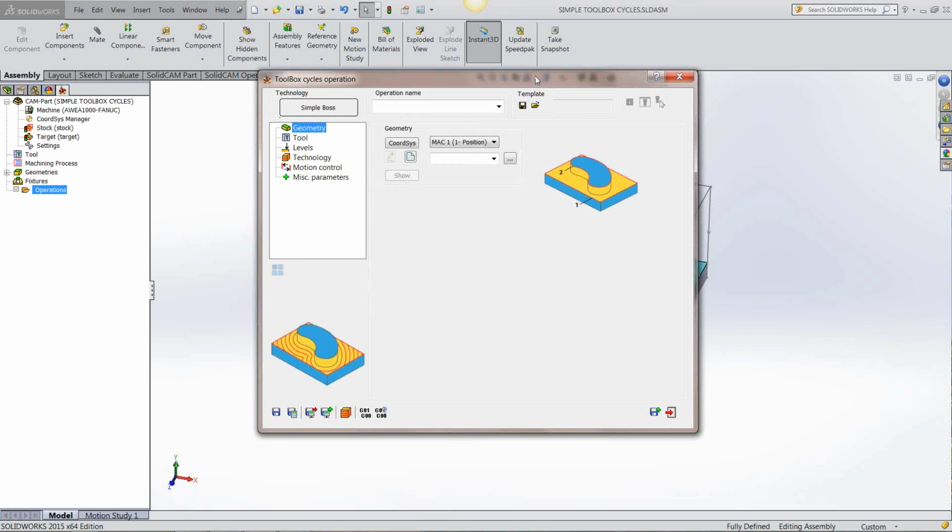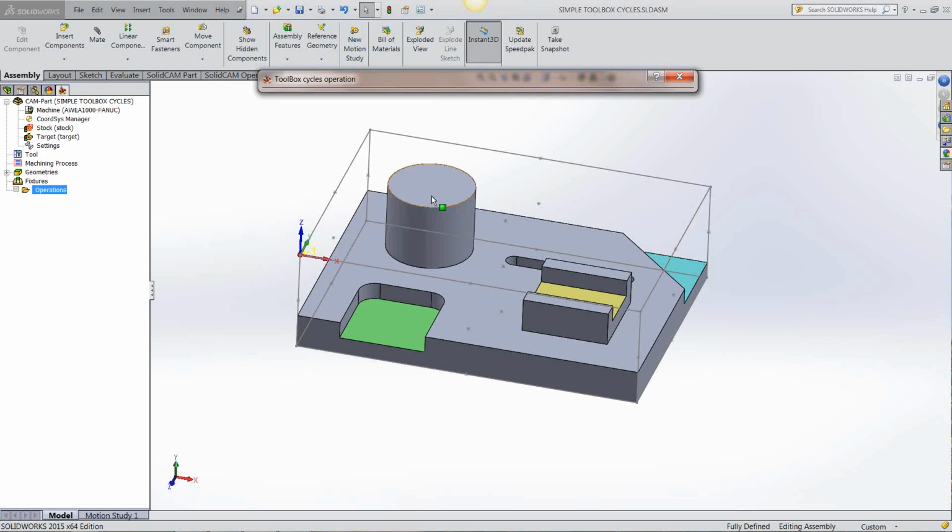What we've got, as you can see, is a boss sticking up on the part. If this little rectangular feature wasn't there, then that's exactly what that is. It's a simple boss. But I've got to take into recognition that this feature is here, so I can only go down to this top level using the Simple Boss feature.